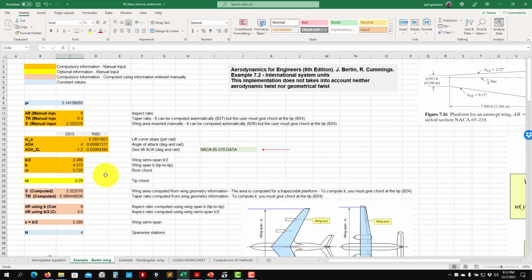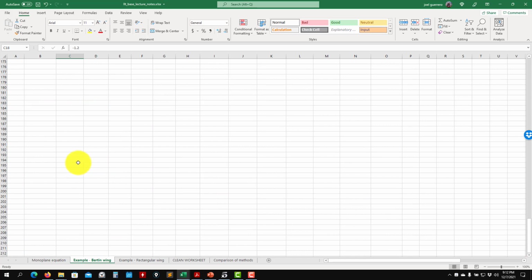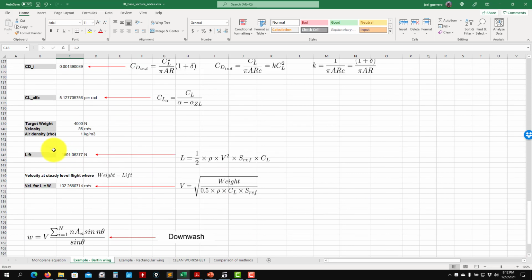You can also increase your angle of attack. So for instance, in this case, we're working at 4. Let's go, for instance, to 1 degree, clear, okay, that the lift will be lower. Let me go back to 1225, sea level, and see that it's half. So to produce the required lift, I need to increase velocity. So if I go at 120, there we are. Okay, this is the minimum lift that we need to stay aloft.